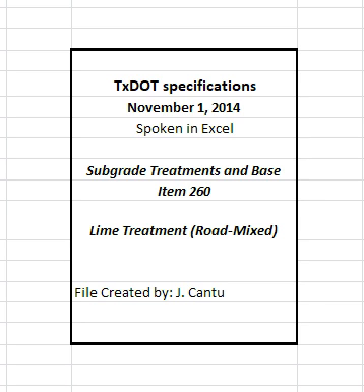Notify the engineer of the proposed material sources and of changes to material sources. Obtain verification from the engineer that the specification requirements are met before using the sources. The engineer may sample and test project materials at any time before compaction. Use TEX 100E for material definitions.